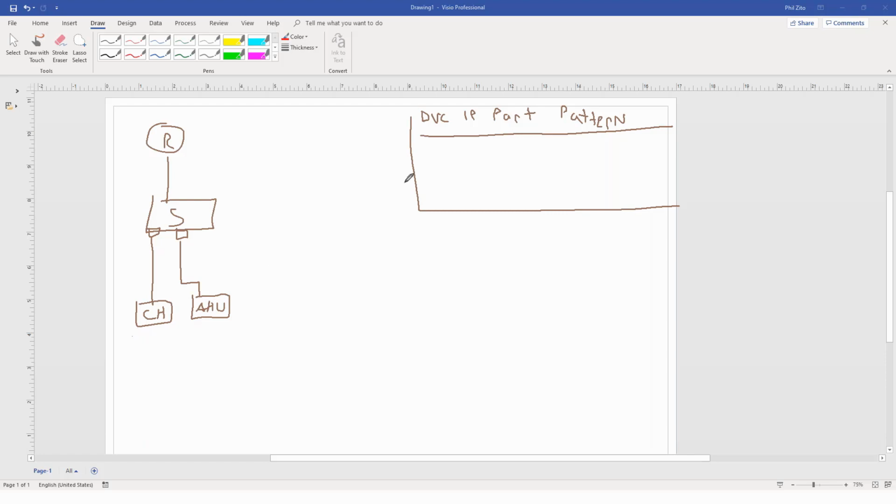And we would assign an IP address, and it's not going to go on the drawing. I highly recommend it goes up here into our device list, and we just simply number. We come up with some form of numbering, whether it's an ID number, whether we're using a BACnet device ID, whatever identifier we want. Because if you start putting IP addresses on your riser, it's going to get really messy. Keep them in a nice organized table, typically in the upper right-hand corner. That's where most folks are comfortable. Sometimes in the lower right-hand corner if you so choose, but I typically recommend up here because that's right where the eyes go.